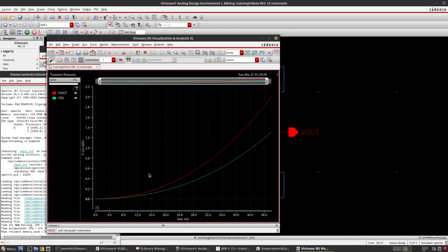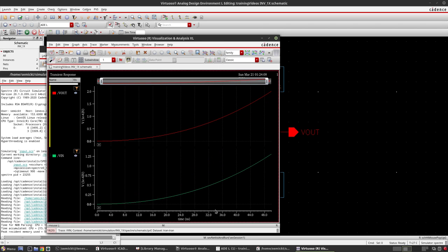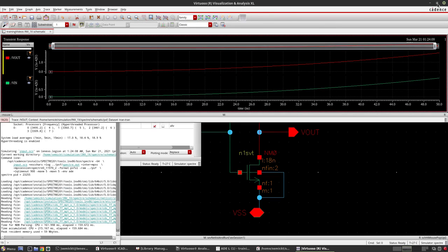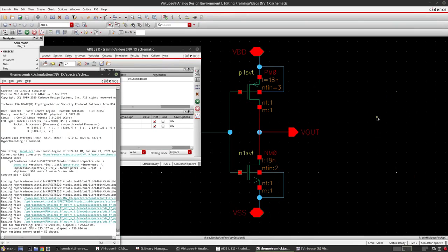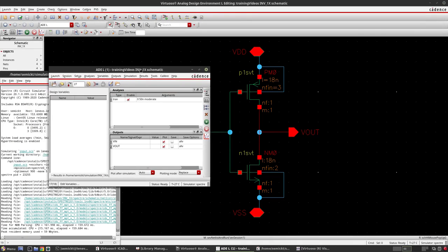So here it says 1e-42 volts. So it is almost zero, right? Nothing is happening. We haven't provided any input waveform, and we are expecting an output waveform. VDD and VSS are also not connected. We haven't given anything, so it is just showing some waveform. Okay, so we'll minimize this waveform window, and now we shall give the inputs and input waveform,